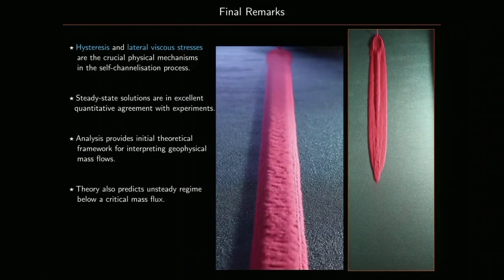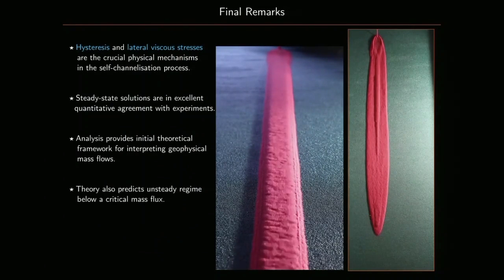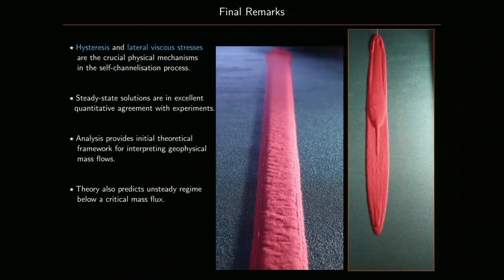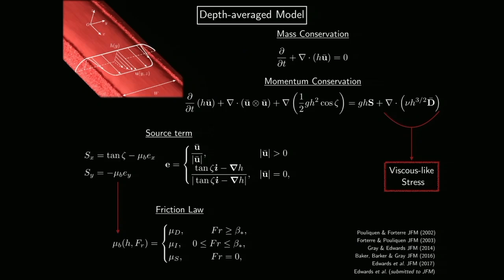When you look at the velocity profile in the x direction on your levees, it looked like your velocity profile goes right from the bottom of the levee to the top surface. But then when you were doing your modelling, it looked like most of the flow occurred in the top of the levee and not down at the bottom.